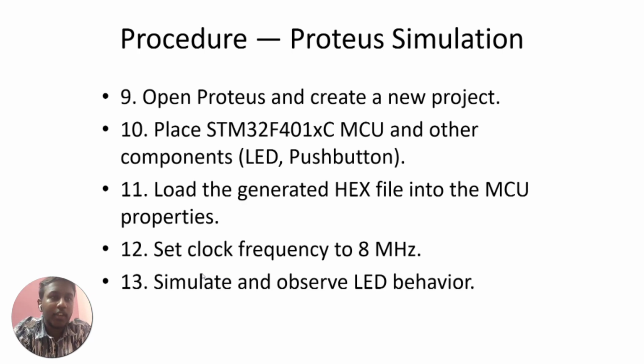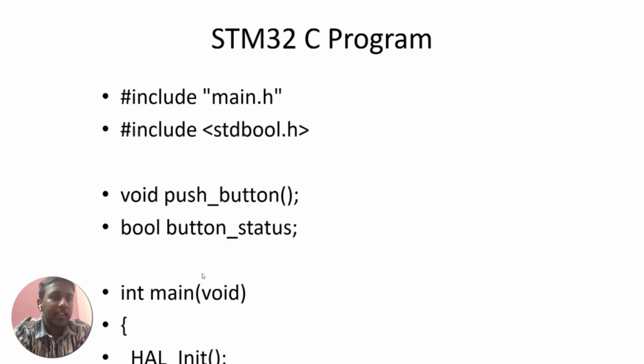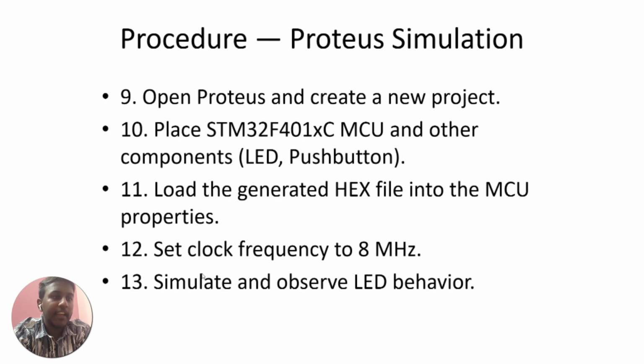Now let's see the Proteus simulation. For the Proteus simulation, open Proteus and create a new project. Place the STM32F401 microcontroller, the LED and the push button. Double click on the microcontroller. Under the program section, browse and load the .elf file that is generated by the Cube IDE. Now when running the simulation, pressing the button should make the LED blink just like it would in real hardware.